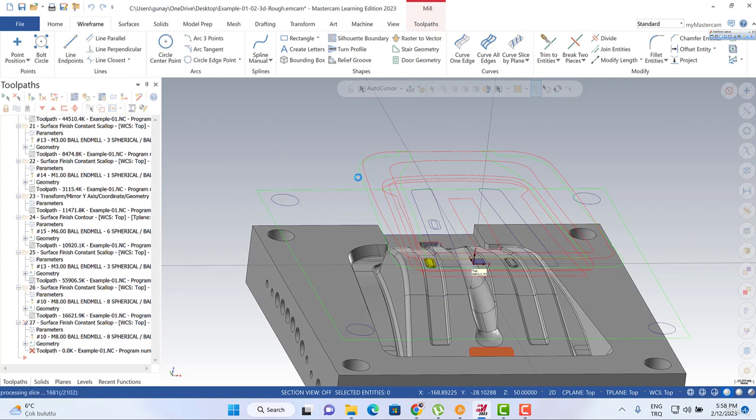So actually, this is the main idea behind how you can create your toolpath. You need to split your face, you need to create your boundary. Maybe you should also create new faces to check or to control your drive surface, and then you can easily create your toolpath. Otherwise, when you turn to the CNC, you're going to see some problem in your toolpath.